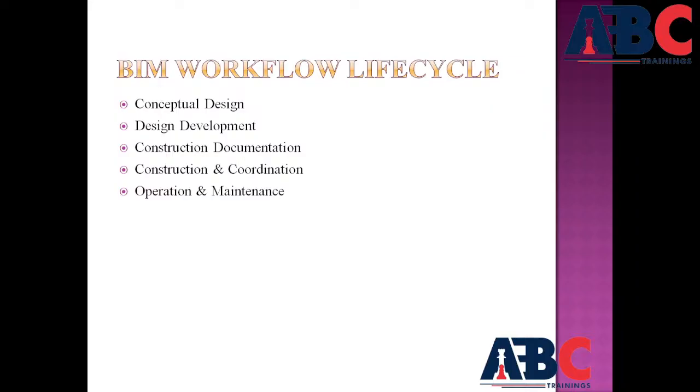Then construction and coordination. So during the project, BIM models act as a central coordination hub for the contractors and the project managers. It helps to track the progress, identify the conflicts, and visualize sequencing, often referred to as 4D BIM. Model based scheduling and construction sequencing, clash detection using tools like Navisworks, on site coordination and quality checks, cost management, and material tracking.